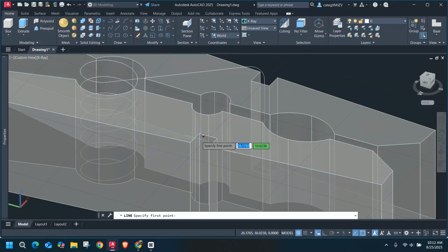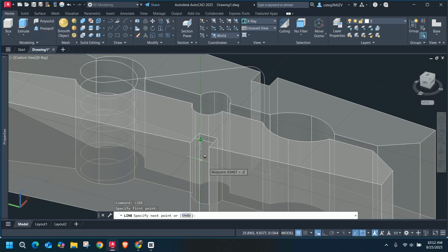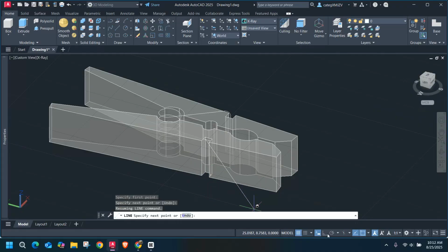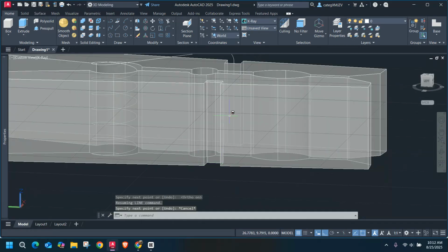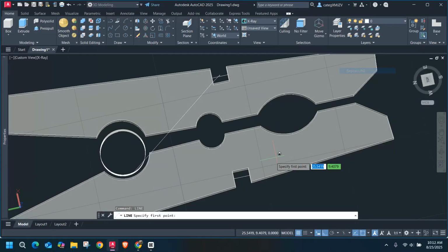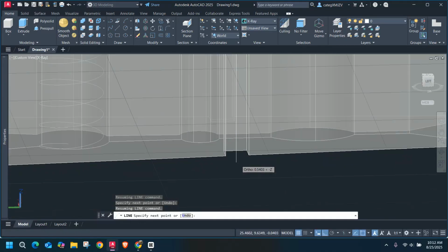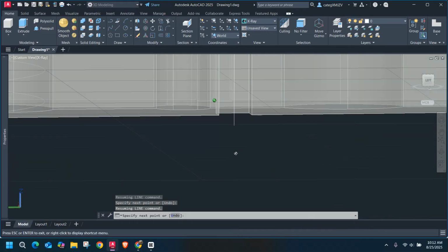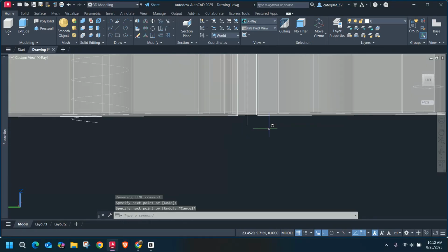So I'm gonna do a line in the middle, just like I did before, across. Then I'm gonna go ahead and do a repeat line down the middle of this, straight down. Make sure your ortho is on, okay? And I wanna make sure, oh, look, I put it somewhere weird. Never good. Okay, let's make sure we're on the right line when I make it. That would help life. Okay, so if we go straight down, let's bring it past. Now, if you know the height of it, you'll know you're fine. And so then I could have another line go from this point to that point, let's say.